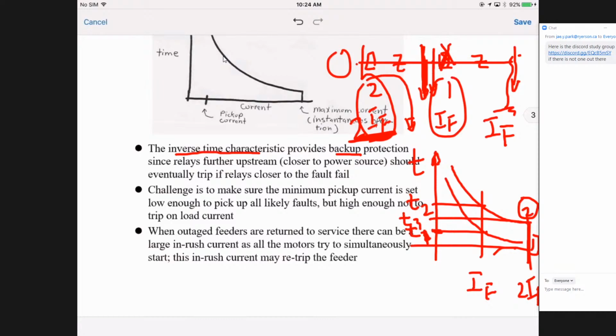Excuse me, can I just ask a question? In this scenario, would the second breaker have a higher capacity than the first breaker? Correct. But the relay does not see whether it is high capability. The CT is still 5A. You just change the turns ratio.